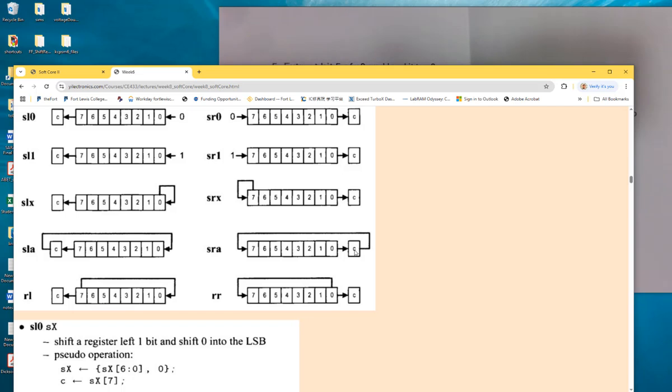Let's write another piece of code for shifting two bits to the right. Can we do two bits? Well, you just have to clear the carry flag, right? Actually, wait, no, you keep the carry flag and then you just loop it, wouldn't you? Yeah, if it's just one carry bit for everything.